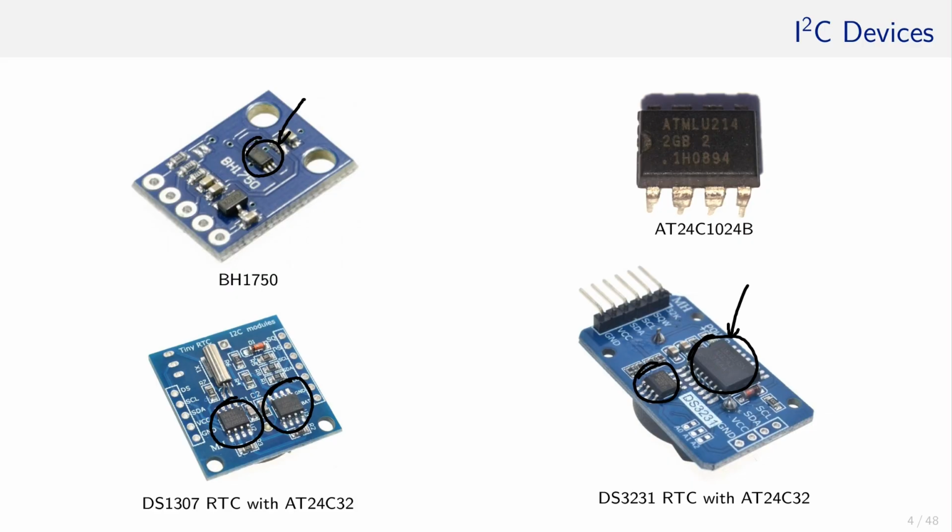While the ATmega 328P also has an internal EEPROM, and we will talk about how to access that a bit later in the course, it might be insufficient since it is only 1 kilobyte in size. Larger, non-volatile memories might be required while keeping an eye on the power consumption. Imagine a remote battery-powered embedded system that records light intensity. If the battery runs out, it will be okay. However, the already recorded data should not be lost.